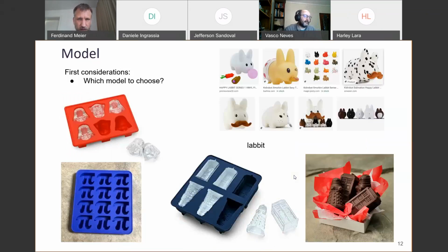This was my attempt. I highly recommend some type of model that is rather small. I'm talking the size of a matchbox or maybe 2 or 3 matchboxes. Once it gets bigger, you will have difficulties finding mills that are long enough because you have to reach all the way down here. And imagine for this one, for milling all those tiny details, you need a mill that is very, very small, and you reach down like 2 centimeters. So that's not very easy to do.